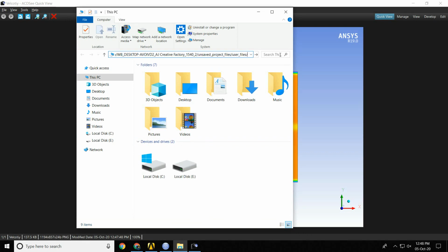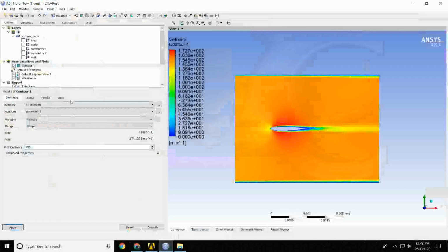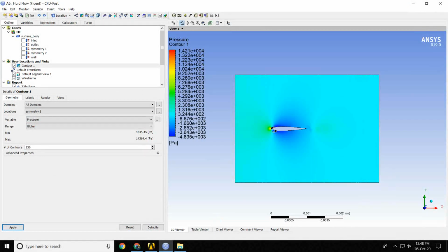We'll go to the drive first. So here, okay, and then we'll see our pressure result. Apply. You can also save this, but this is more prominent somewhere, but the procedure is correct. Okay, so you guys try and get the actual answer. This is your second experiment, which begins from the setup. And please know the boundary conditions. The boundary conditions are laminar flow with an inlet velocity of 150 meter per second.